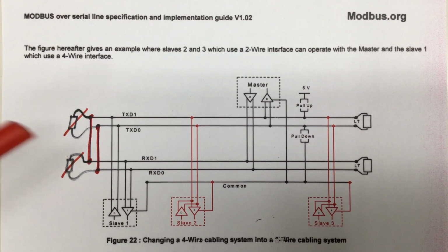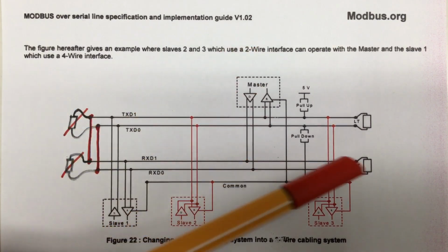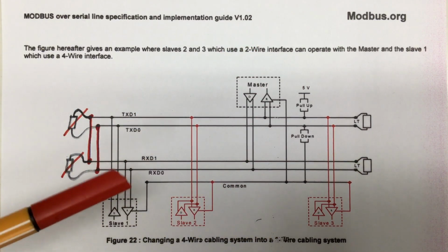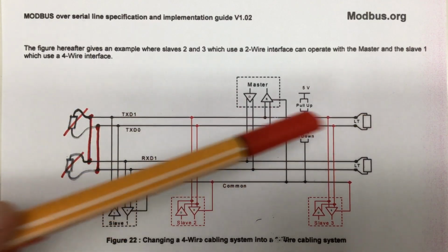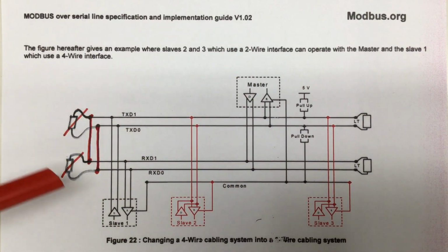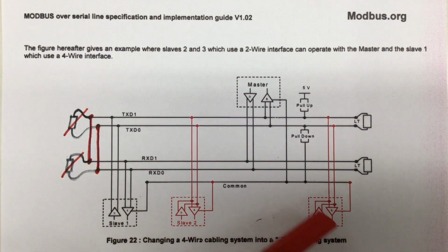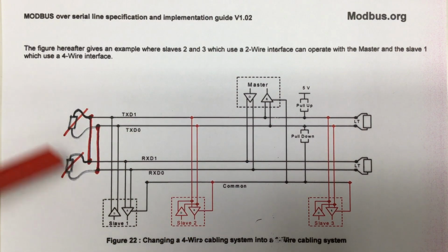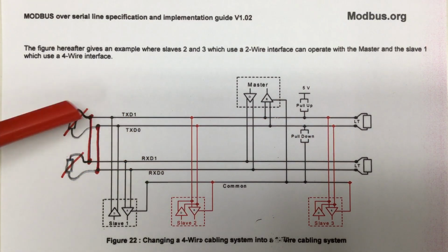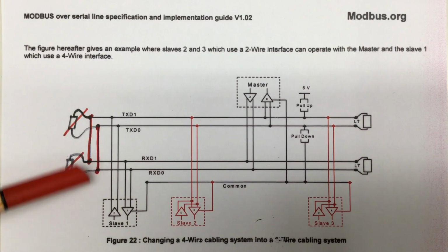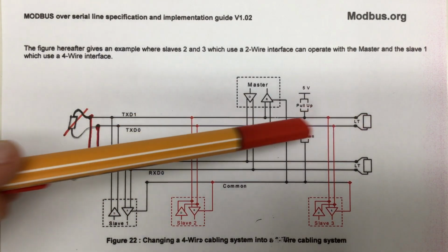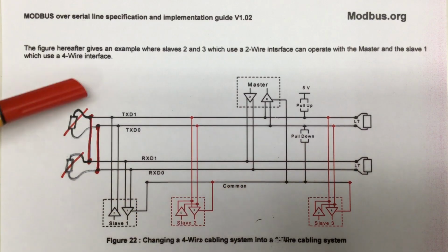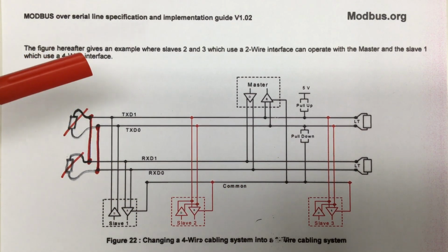So initially you have a full duplex system with a master to slave transmission line and a slave to master transmission line, both of course terminated at both ends. If you want to now connect half-duplex transceivers to your full-duplex system, you simply delete the termination resistors at one end and connect the slaves to master and the master to slaves transmission line, turning it into a single half-duplex transmission line. Yeah, that's it.